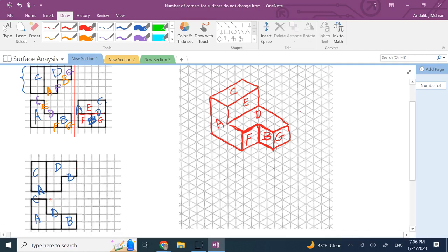Or before that, do you want to determine where A, B, C, and D are in the right view, then we go about it? Well, yes, we can. So first of all, if there is a right view, where would it be? Well, you know the right view is going to have 4 units of height and 4 units of width. And there will be a 1 unit gap between that and the front view. So if you leave a 1 unit gap, the right view should be limited to this 4 by 4 square, basically. The right view should be inside that 4 by 4, right? That's where the right view belongs.